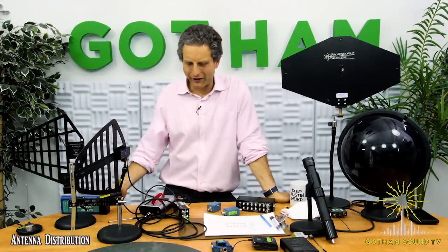But yeah, I mean, I think if you can plant an antenna and get close to your desired signal, that's going to be good. You know, RF output power and link budgets also go to setting your transmit power. So if you're really on top of your talent like that, that's also an opportunity to turn down your transmitter power, so you're not overloading that amplifier in the receiver.